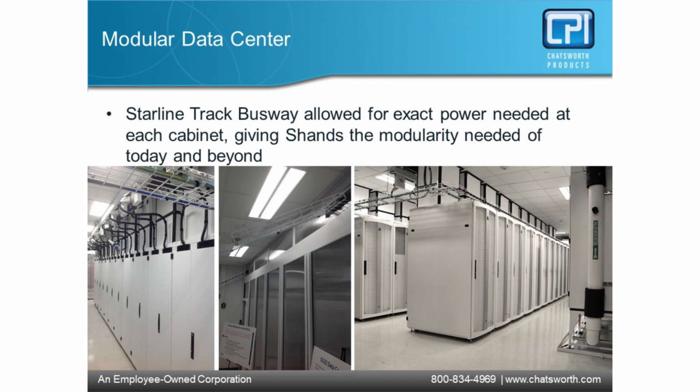One of the other questions that came through, Stephen, was as far as highest ampacity of bus that we have available, and that would be our 800 amp product. And we have ranges, but primarily in these types of applications, the big ones that we sell into this space, we have 100 amp, 225, 250, 400, and 800. Those are the ranges of bus that we have available for these types of applications.